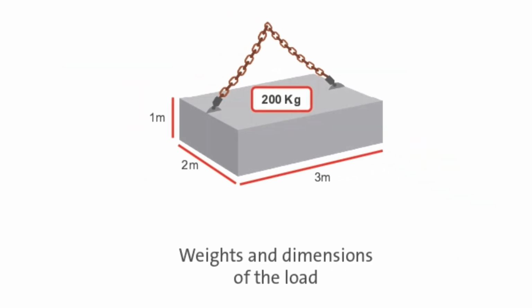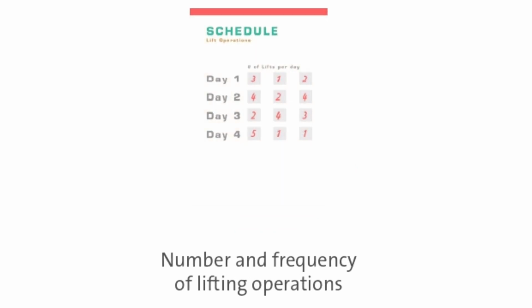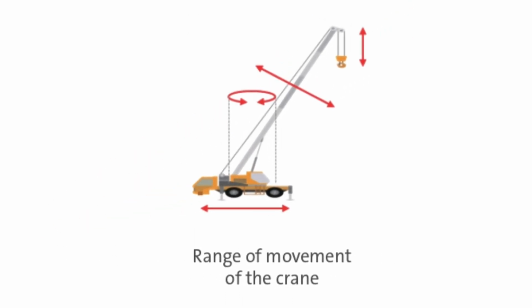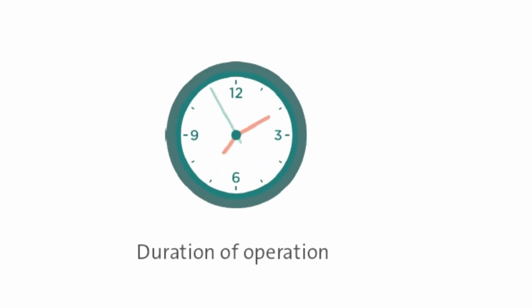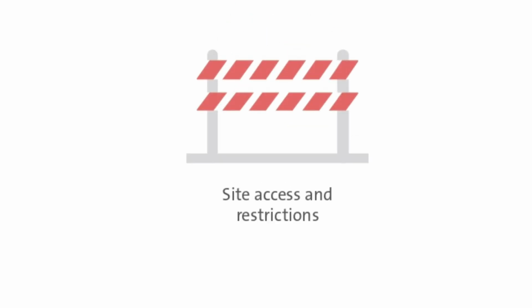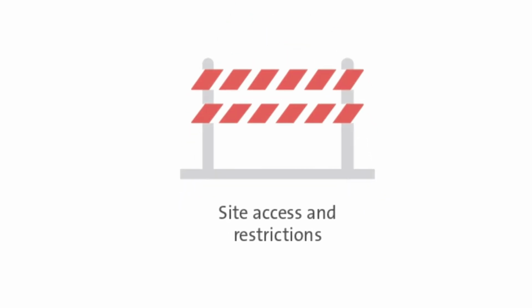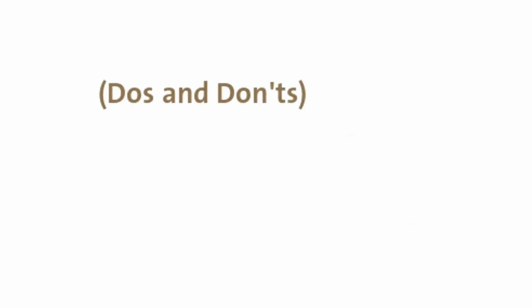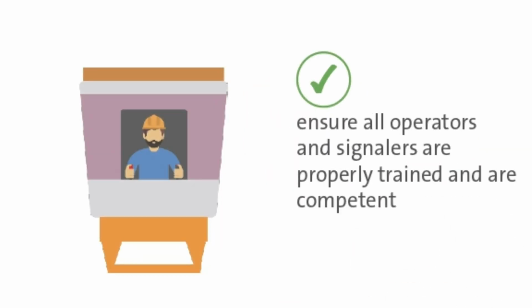Planning crane operations. 1. Weights and dimensions of the load. 2. Number and frequency of lifting operations. 3. Range of movement of the crane. 4. Duration of operation. 5. Site access and restrictions. 6. Available space for erection and dismantling.